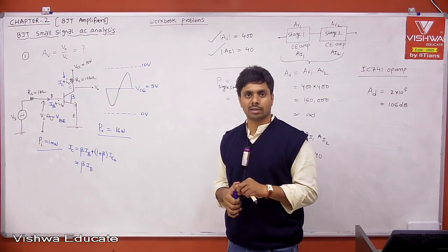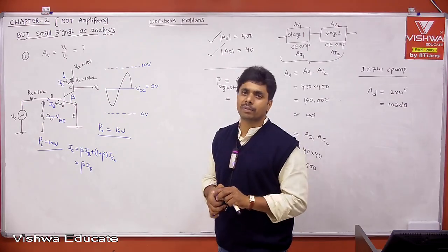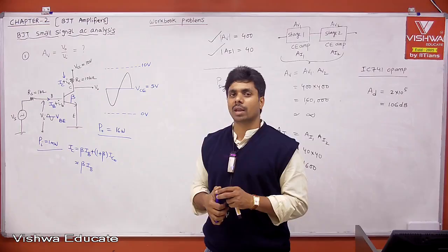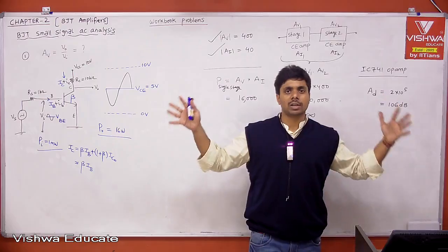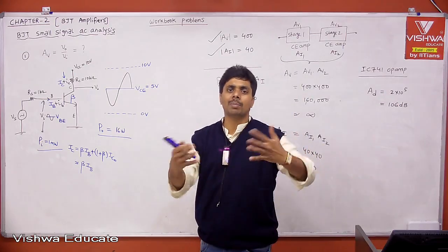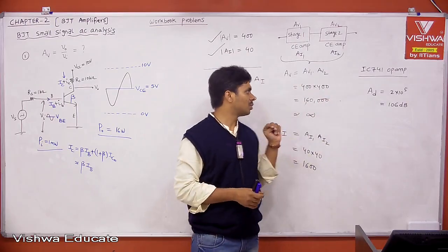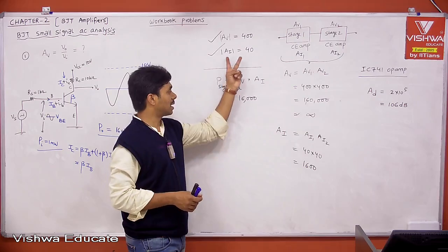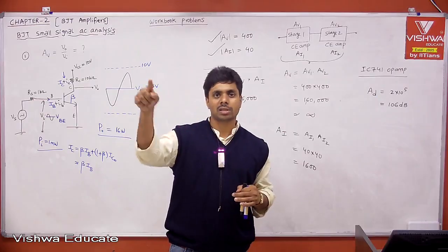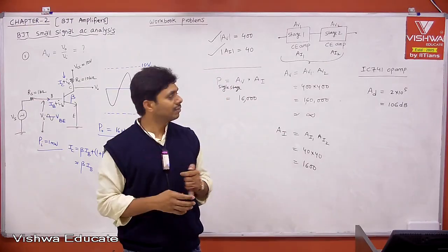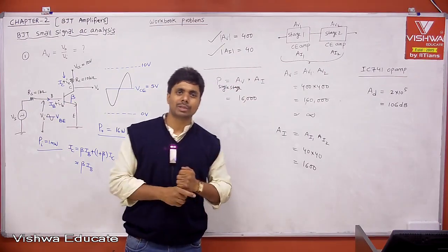Okay. With respect to an audio amplifier, a single stage amplifier is good enough, because you are having power gain. But if you want to design a generic amplifier like an op amp, where I want huge gain, so that I'll use that op amp in many applications, then to get generic amplifiers like op amp, we want two stages. Therefore, two-stage voltage gain, power gain, and current gain are too significant. I can say your common emitter amplifier passes with respect to voltage gain as well as current gain. Right? Everybody understood voltage gain and current gain.